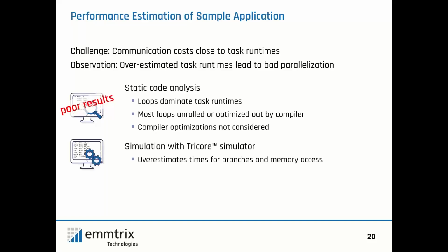So we tried the simulation with the TriCore simulator. If you have a good simulator, this is a very good approach because you don't need to have any hardware and you don't have any overheads from profiling the code. But in our case, the problem was that it overestimated the times for branches and memory accesses. Therefore, we also got poor results with that.